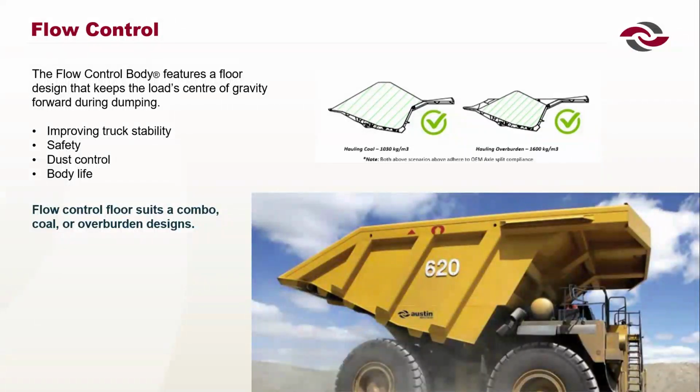I think a few years ago, a customer approached us with a problem. The truck had short wheelbases, and when they dumped material, the entire load center of gravity shifted behind the rear axle, lifting the front wheel off the ground. It's a serious safety hazard. Everybody knows that. So our engineers developed a solution by designing angle flows. We ensured the CG stayed forward during discharge, and we even built a scale model to validate the dumping sequence before manufacturing the first body. The result was a patented flow control design.